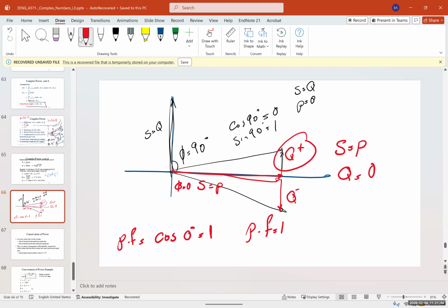But yes, exactly. The problem with reactive power is that it causes loss in the system, and that loss translates to heat, and it would damage the motor. The motor would work initially, and you won't see any problem. But in the long term, you would see the motor heating up pretty quickly, and it's going to damage the wiring, melt the wiring, and so on.